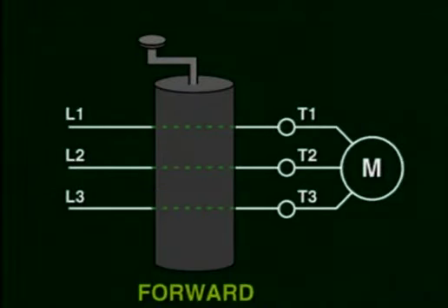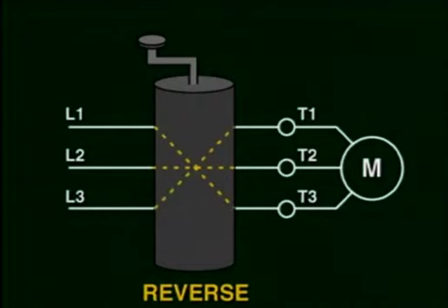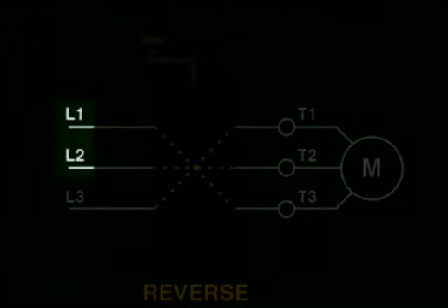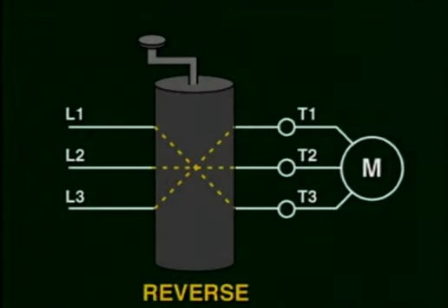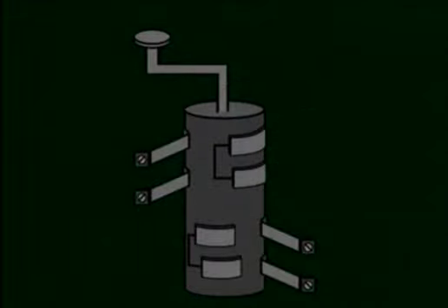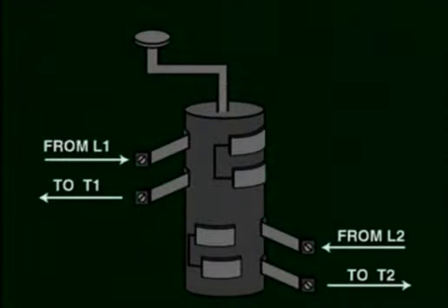When the motor has 3 phases, L1, L2, and L3, connected to the motor terminals T1, T2, and T3, the motor will rotate in the forward direction. By switching 2 of the phases going into the motor terminals, let's say we switch L1 and L3, the motor will rotate in the opposite direction, or in the reverse direction. We could have switched L1 and L2, or L2 and L3 to their respective switch terminals, and the results would have been the same. The drum switch provides you with a mechanism of making the line switches to the motor terminals easy to implement and operate.